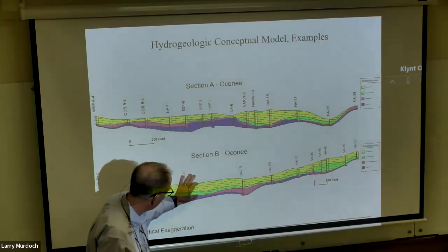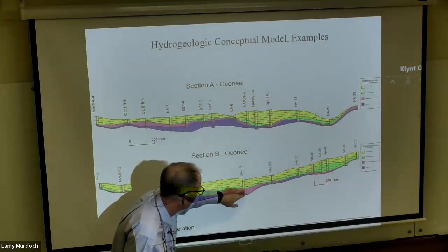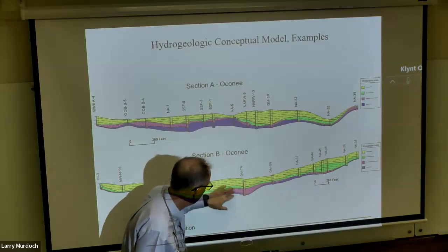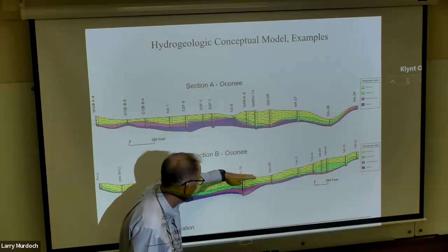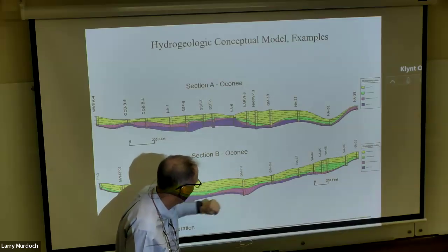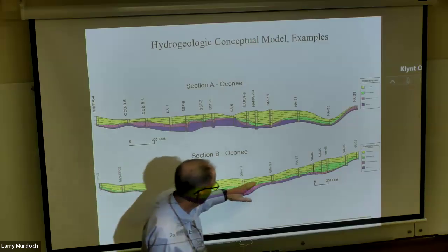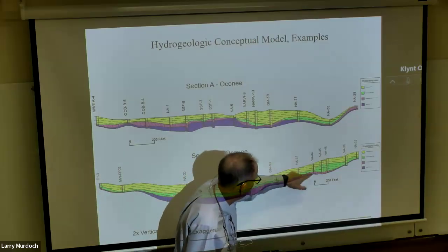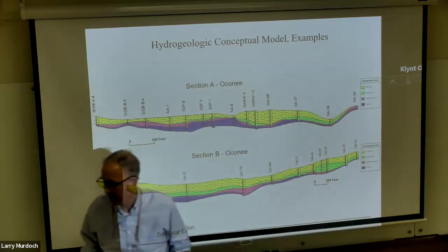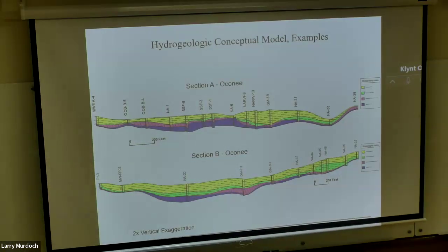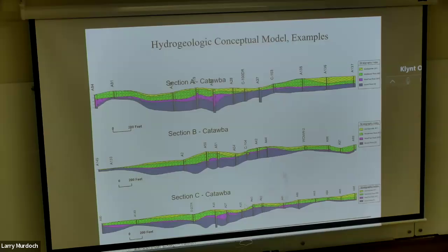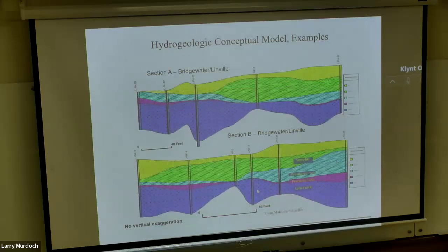And here we see something similar. Here we have the thickness of the saprolite, and then we pick up the transition zone getting thicker. Here it's pretty much a flat area, but we have this thickening of the transition zone. Then as we go upslope, we get these different units coming in and out. So it's variable, but it's hard to come up with rules of the variability that are followed consistently. Here are some other cross sections of the variation.